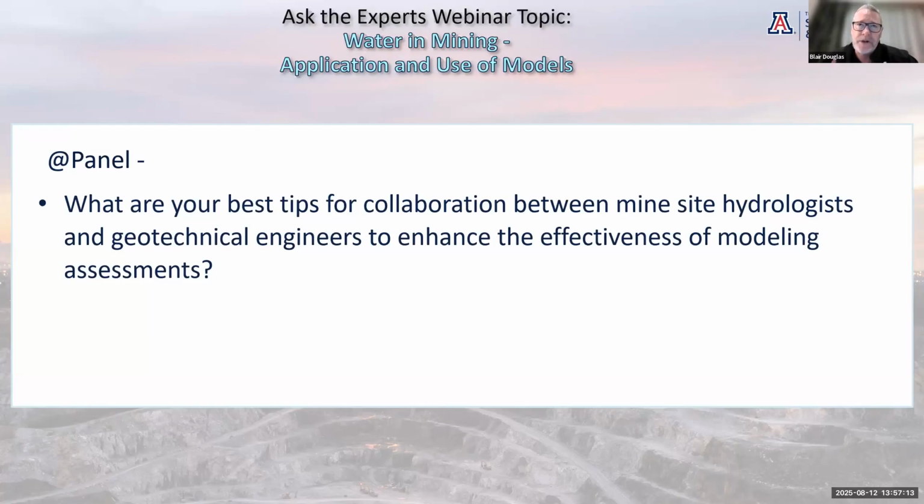So then you can actually structure your monitoring network to be within that range of detail, because there's no real point in having a very detailed hydrogeological section in areas which don't matter, but also vice versa. If it's a complex geotechnical analysis and you've got one vibrating wire, it's not enough.